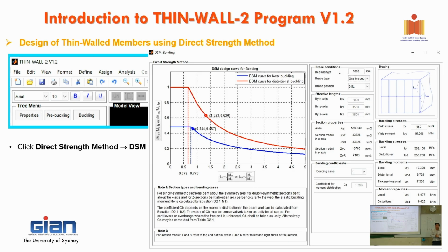Longitudinal variations. How long? Longitudinal. Cross-sectionally, your thickness is constant. So when you consider around the length, how will that variation be considered? That is a tricky one. It's hard. At the moment in finite strip, we consider a uniform stress along the strip. I think the other way you can do is ply finite strip or something. With ply, we can make it better, closer to finite element.